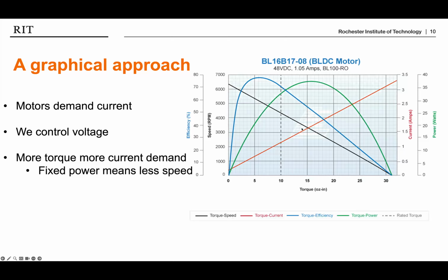And that makes sense, right? Because after I cross the midpoint of this black line, the torque values might get larger, but the speed is starting to get smaller and smaller and smaller. On this side of this point, my torque values are smaller, but my speed is still fairly high. So my balance point for this whole thing, my peak power, happens to be right in the middle. And that's a pretty neat and useful fact.